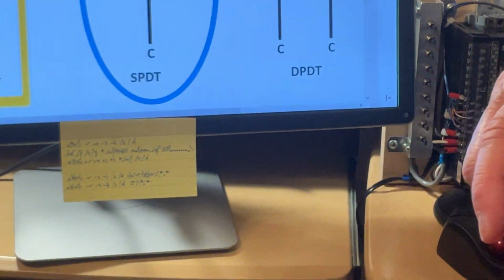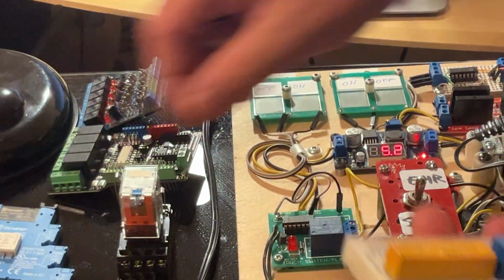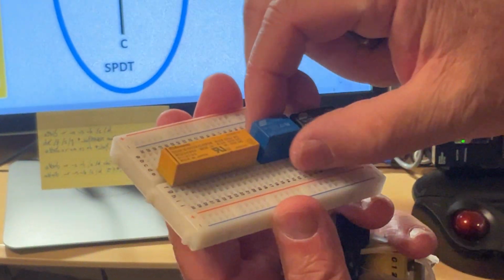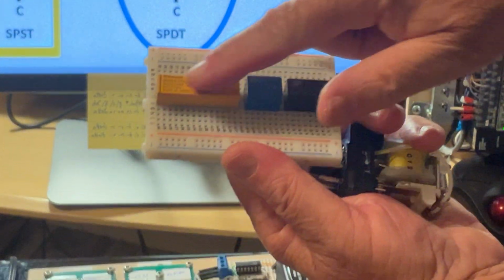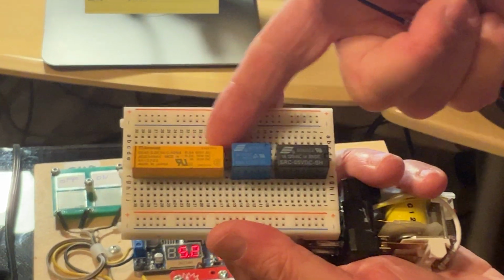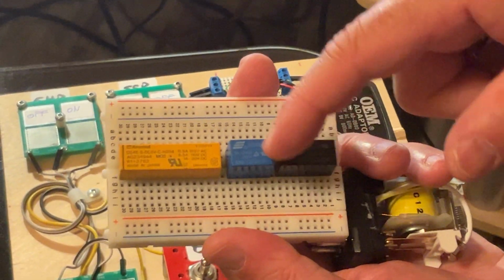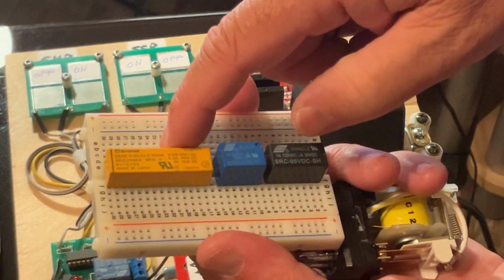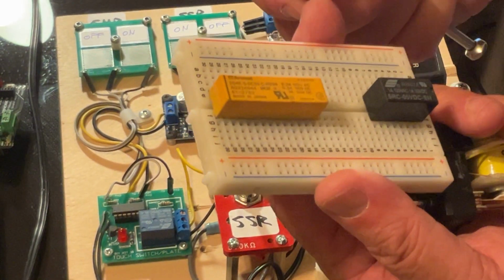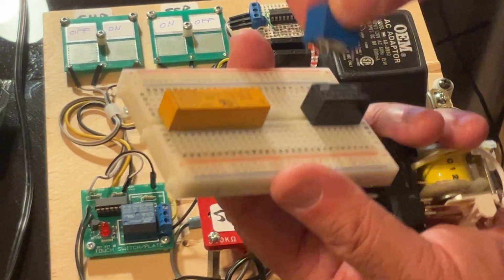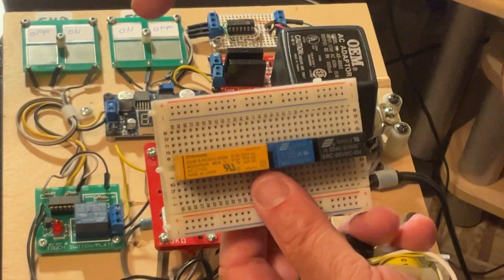Or, even better for our projects, you can have this kind of arrangement, this one, where the relay, if the pins are placed properly, can be placed on a breadboard, so we can check our projects before dealing with the final object. And that's a very friendly arrangement for us. It's completely sealed. You don't have to deal with the elements of the relay, excepting to take a look in the specs to find out what the pins are for, okay? How to connect the pins.